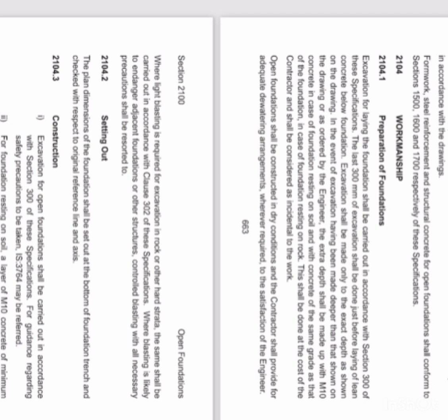In the event of excavations having been made deeper than that shown on the drawing or as ordered by the engineer, the extra depth shall be made up to with M10 concrete in case of foundation resting on soil and with concrete of the same grade as that of the foundation.